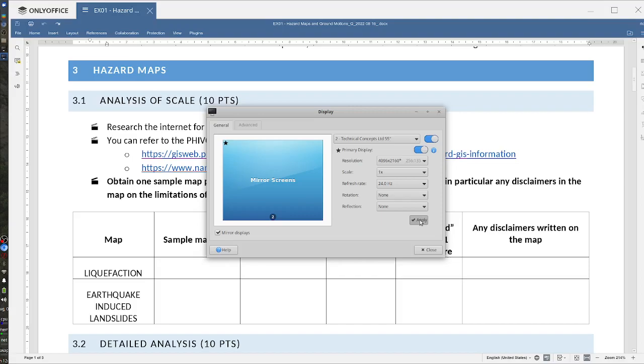So once they reach this basin, the waves reach this soft sediment and will disperse. Once the waves reach the edges of the basin, which is a stronger or stiffer rock, they usually undergo deflection. So in general, the whole seismic wave will be trapped inside the basin. Amplified, sir? Yeah, it can get amplified.